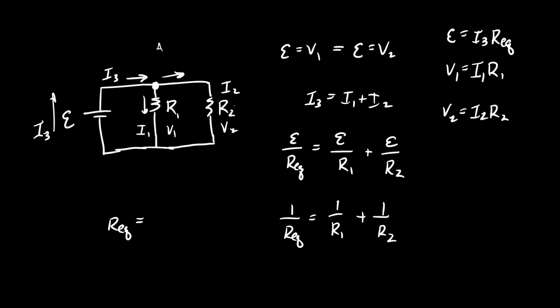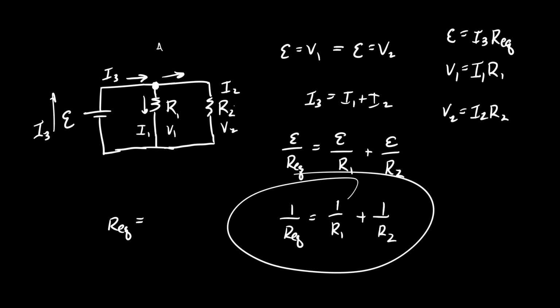Since what we're getting at is a way of writing the equivalent resistance for our circuit, I think trying to get the equivalent resistance is our goal. Does this not look familiar to something we've already done? I mean, this is exactly what we did for capacitance, right? Almost point for point. That's why it's a little frustrating sitting in this chair, because we did this already. But if you're paying close attention, you will notice that it's the opposite for resistance as it is for capacitance. Resistors in series, you sum the resistance. Capacitors in series, you have to deal with the inverses.